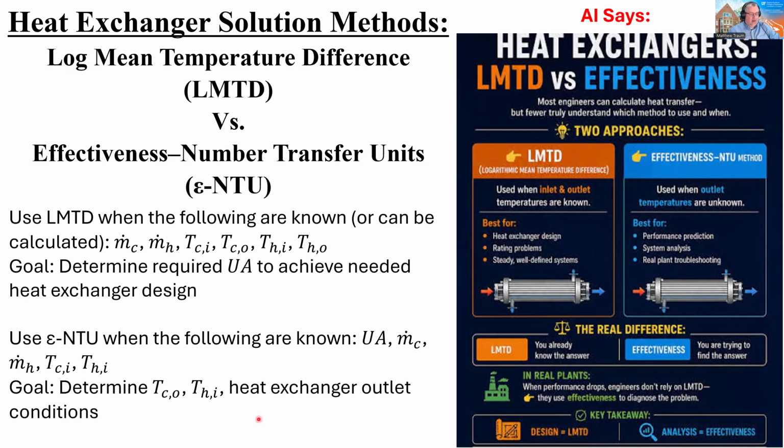And the thing that's kind of interesting about this is LMTD is predicated on the idea that you can apply the first law of thermodynamics, right? You basically know all of these things with the exception of one, and you apply the first law of thermodynamics, and out pops the one thing you don't know. With the Effectiveness-NTU method, enough information is withheld that if you just sort of blindly apply the first law of thermodynamics, you would not actually be able to get the output conditions.